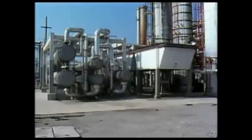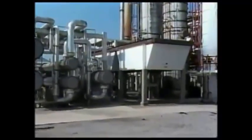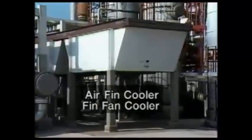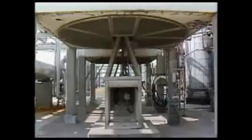To get a better understanding of how heat transfer occurs in a heat exchanger, we'll use this heat exchanger. It's called an air fin cooler, or a fin fan cooler. It's used to transfer heat from a process fluid to the air that flows through the cooler. The cooler consists of a series of tubes, each of which has thin metal fins. The heat exchanger also has a fan.